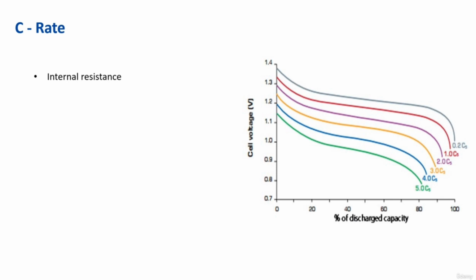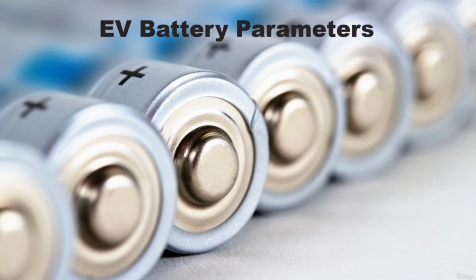The dependence of the charge and discharge voltage on the current also has consequences for the capacity. This is because both charge and discharge capacities are restricted by the so-called cut-off voltages, V minimum and V maximum. This is to protect the electrode and electrolyte materials from degrading, which typically results in a shorter cycle life and lower energy efficiency, which again will be discussed in the next lecture.